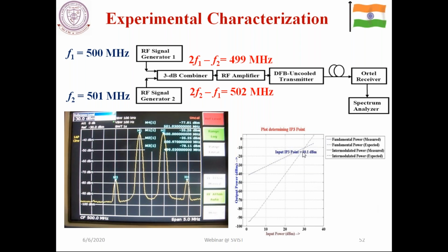Okay, so the basic thumb rule is that you have to operate much below the power which has been characterized by the third order intercept point.